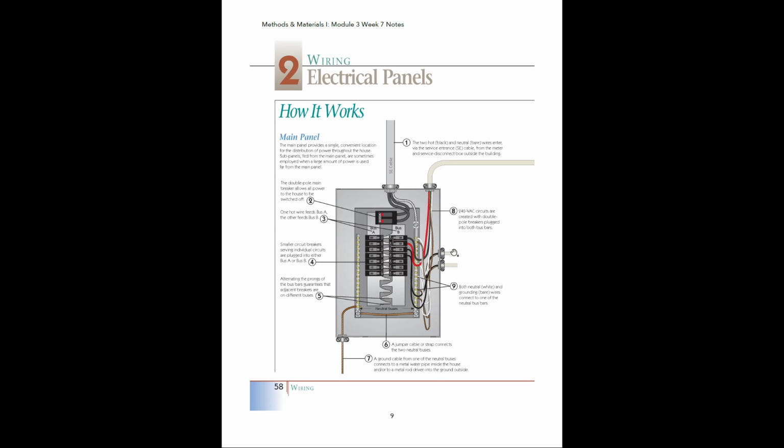Usually there's a bunch of different wires running off of this. Each wire is going to represent an individual circuit that's running out to the house. The hot wires are the black wires here, and the ground wires are going to be tying in to these sides here. Well, the neutral wires are. These are what are known as the neutral buses.